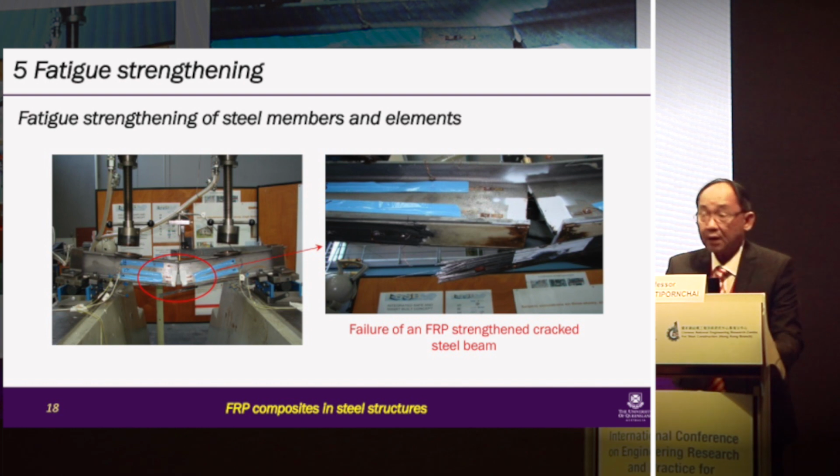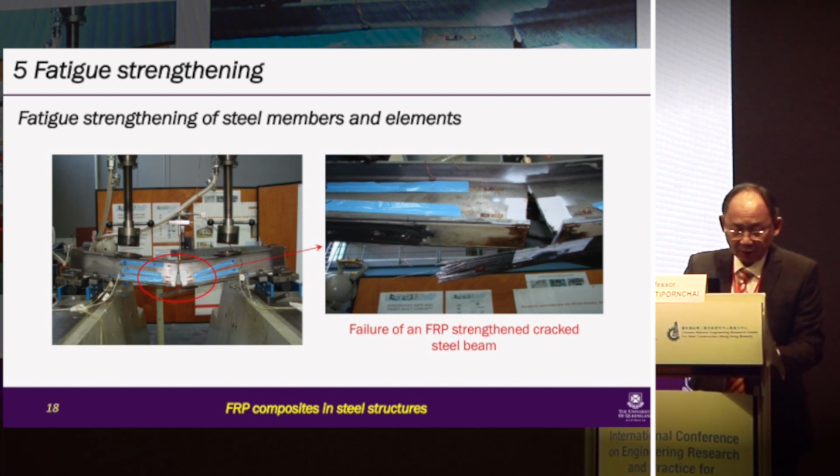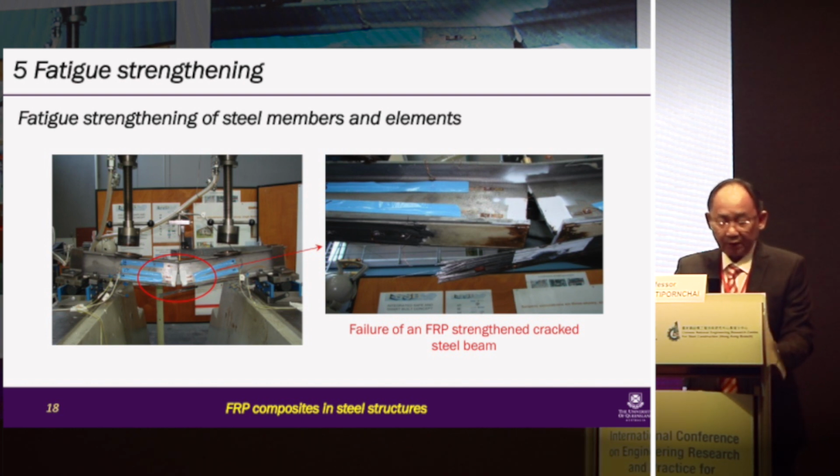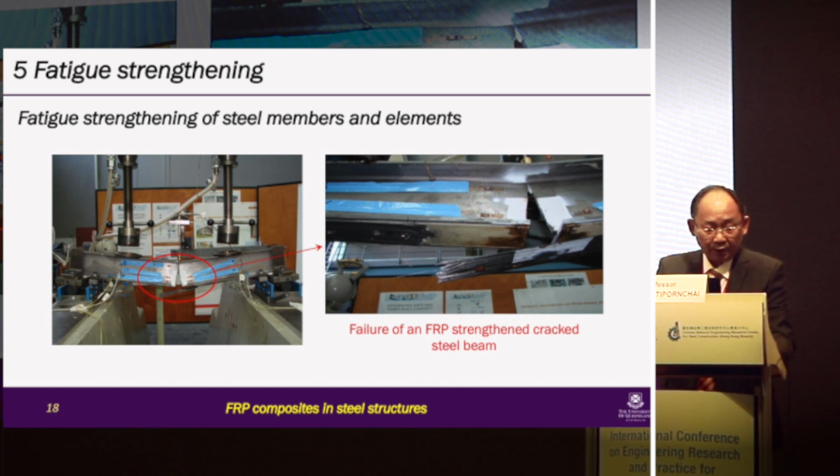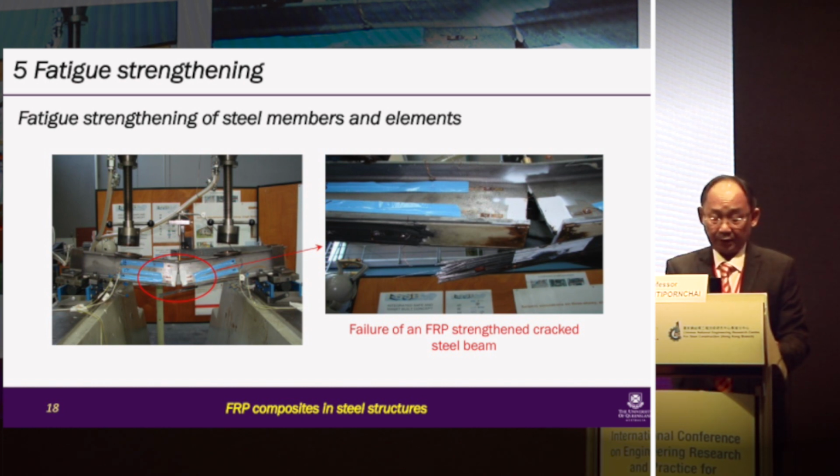Now, this is a test done by my colleague, Dr. Dylan Fernando, which showed failure due to debonding followed by rupture. The application of the pre-stressed FRP plate has actually increased the fatigue strength quite significantly.